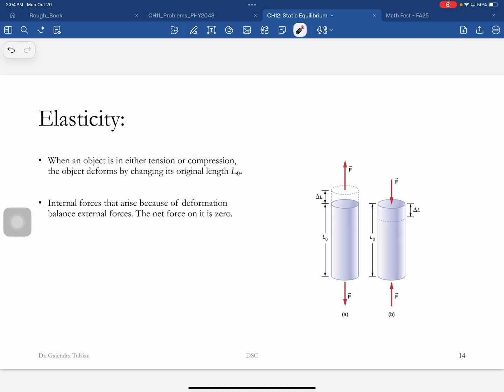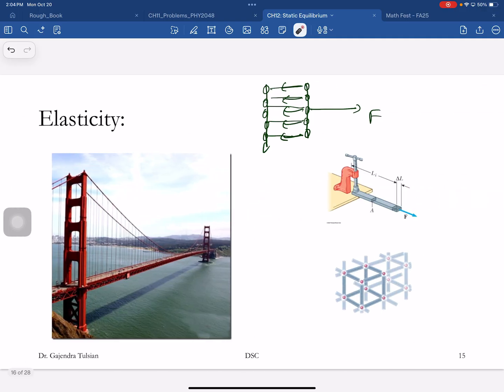What does that statement mean? If you pull on it, it'll snap. If you press on it, it won't break. So you need almost a 10 times compressive force to break it. All right, what does that mean? If you're building any structure, and your structure is to bear a large force, it had better be a compressive force. Smaller forces you can let tensile stresses handle. Large forces had better be compressive forces. Okay, let me show that to you in this example.